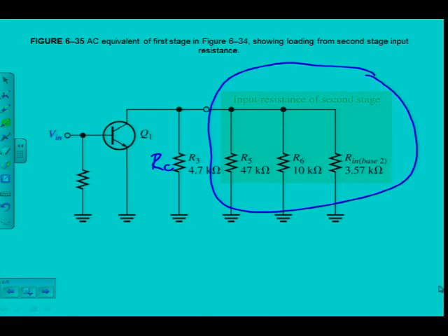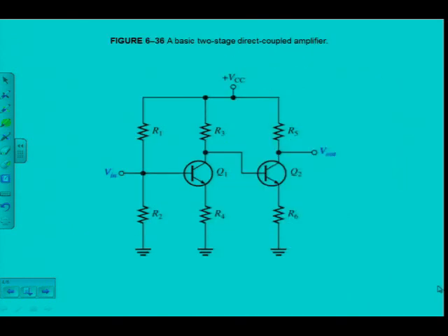Alright, the last thing here is, remember this amplifier that we've discussed was a capacitor coupled amplifier. Now you also get the multi-stage amplifier, which is direct coupled multi-stage amplifier. The direct means there's no capacitor between the two stages. And now can you see what makes it different? Here's my first stage of amplifier. Up to there's my first stage.